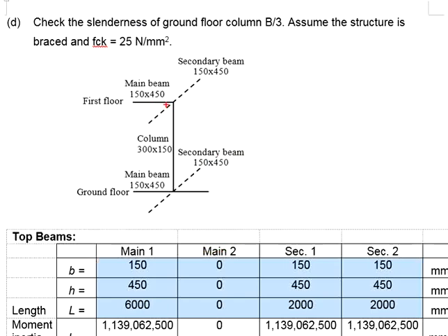You see, a typical column has two ends. Each end meets a joint. When the joint is subjected to a moment, due to the stiffness of the column itself, the column shall share part of the moment acting on the joint. Depending on the relative stiffness over the total stiffness of the connection, you will be able to get the moment taken by the column. Both ends might have different setups of the connections.